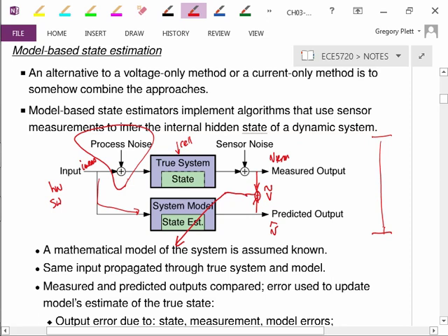In a negative sense, it's the noise on the measurement and so forth, which actually does impact the model, but not the true system. But we can basically lump it together with the noises going into the system for our purposes. So there are things affecting the true state that I don't know about, and furthermore, there's things affecting the measurement that I don't know about, the sensor noise, and even some modeling error we could put in there.